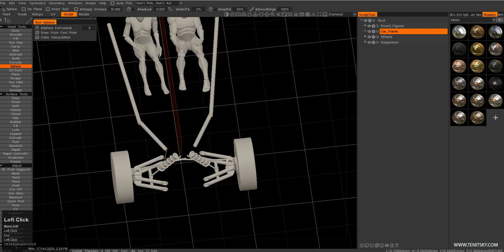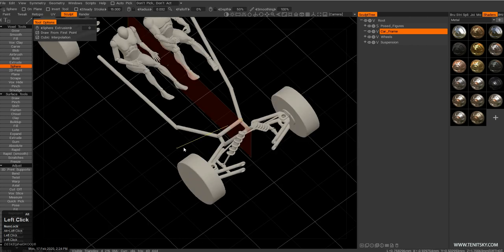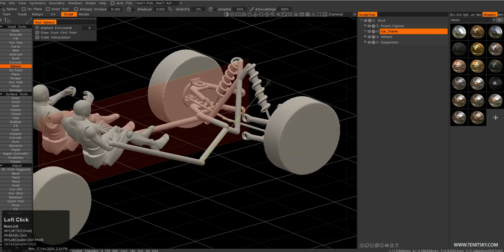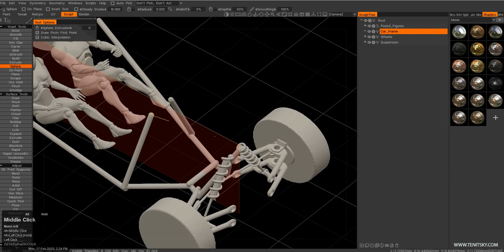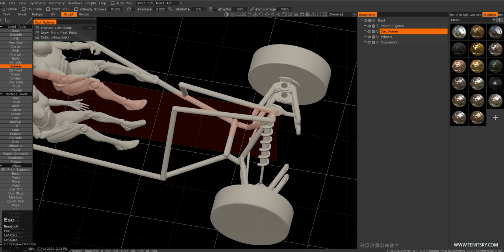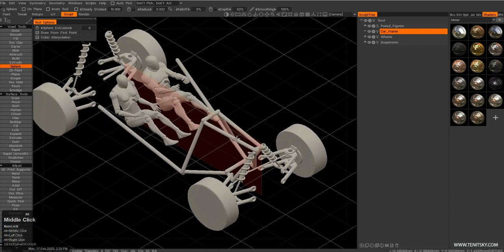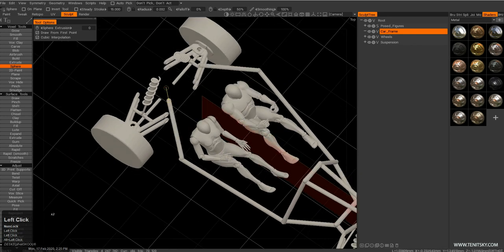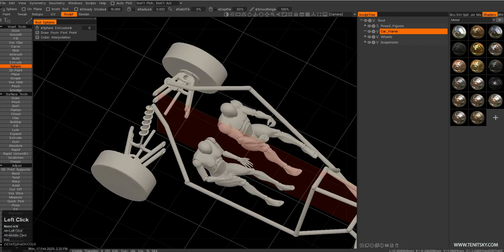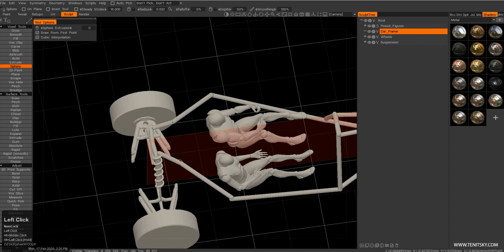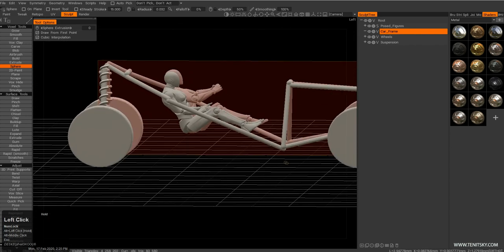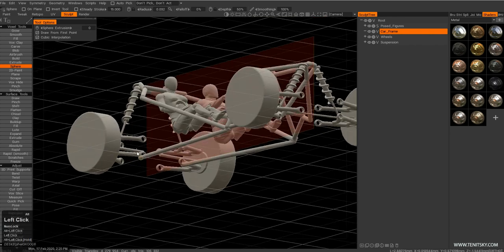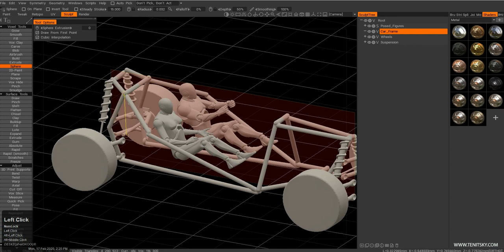The car frame, I would say, just follow common sense, how it would hold the weight. And again, looking at the reference of car frames of different vehicles is quite beneficial. Do check more ATV vehicles, racing cars where they have custom-made frames, because that allows them to build this type of frame. Since more mass production cars often have unibody and monobody frames, they are really different from this, and it's not really my intention to make a mass production unibody buggy. So I'm looking for the points to connect my parts, my frame structure.